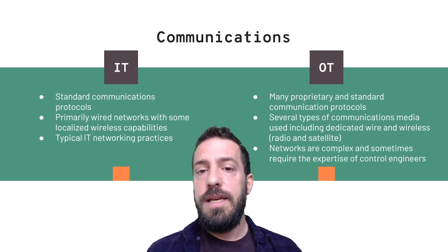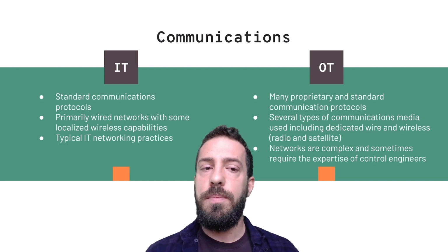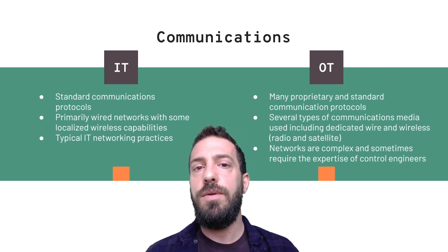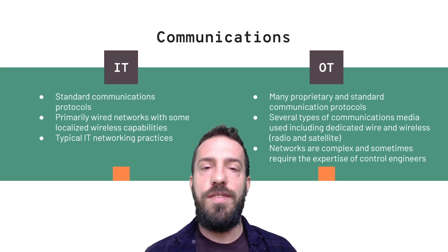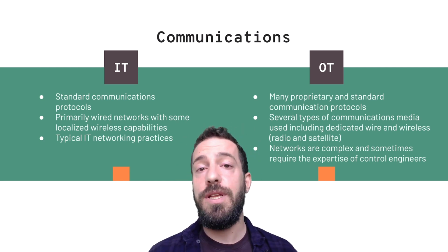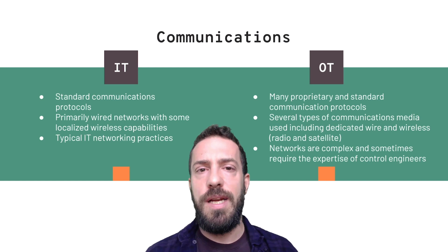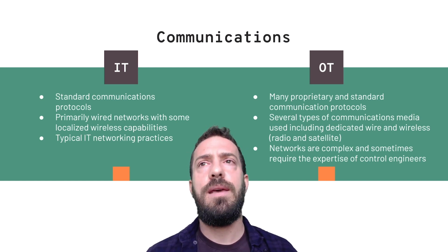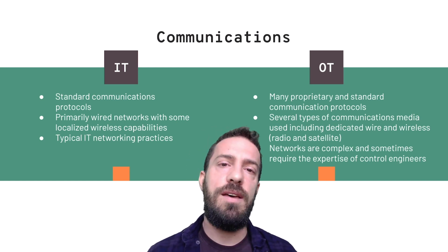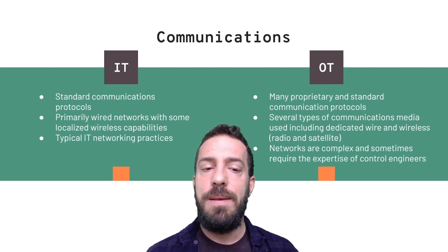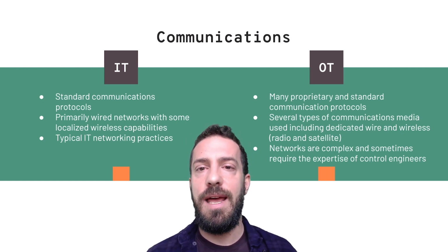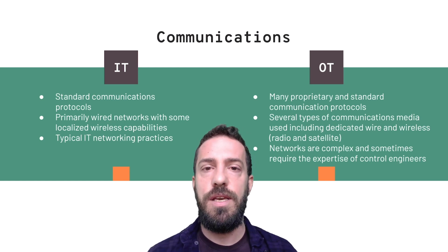Another difference is communications and the protocols used in the IT world and the OT world, right? In the IT, we're very familiar with TCP/IP. There's also UDP, and that's about it, right? And for the medium, the physical layer, we have Wi-Fi, we have Ethernet, Bluetooth maybe, but these are all very standardized, and every device we have uses them.